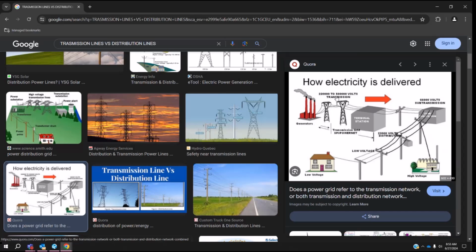It all has to do with the quantity of current, the quantity of electrons flowing through the conductor. If I can minimize that, where I've got a couple of milliamps or 1 or 2 amps going 500 miles, I'm going to have a lot less energy loss at that high voltage, low current, over 500 miles, than I am at these lower voltages, like 12470, when I'm pushing 60 amps down this conductor to the house. Because these distribution lines, they'll go for 4 or 5 miles at 12470, 35 kV, stuff like that.